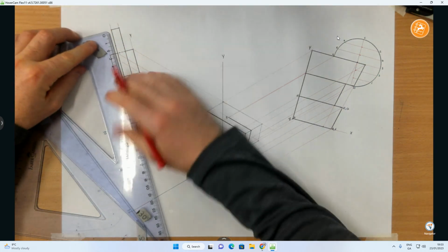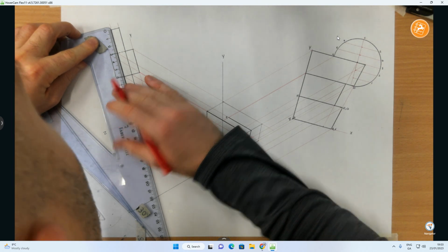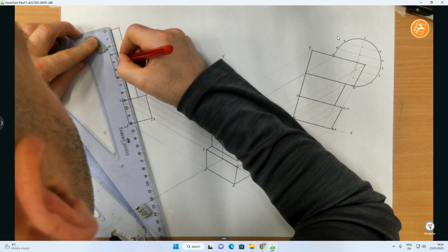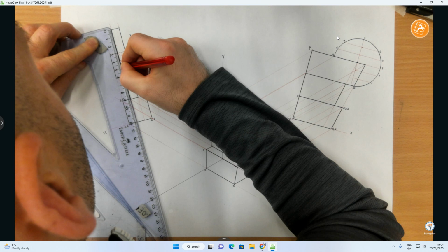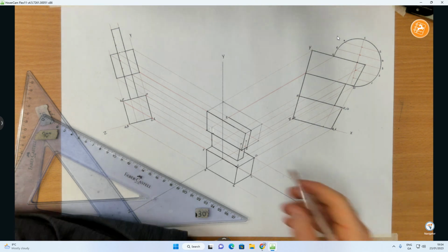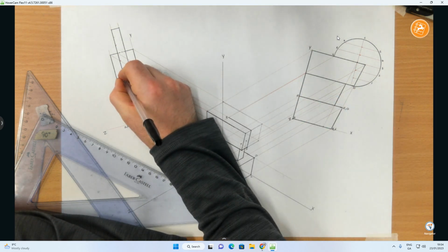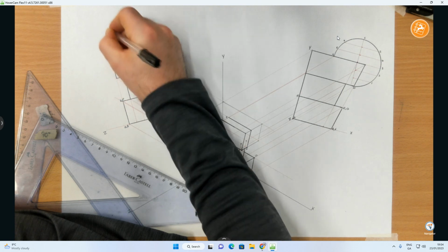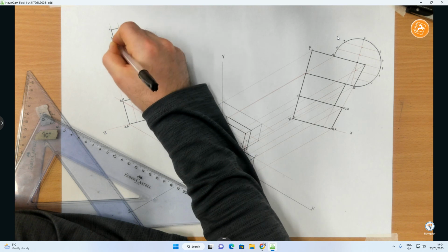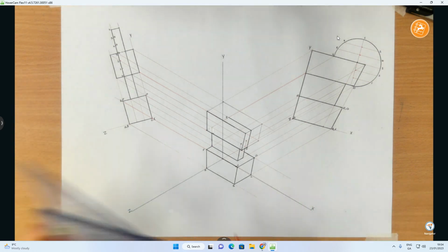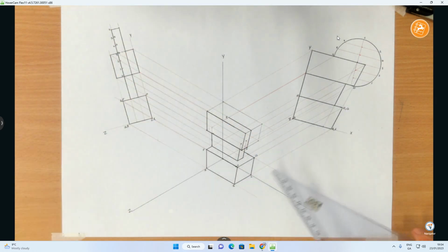So remember, it's this face that we're seeing first. So measuring down in tens: 10, 20, 30 is done already. There's the 40, and there's the 50. Using that principle, same measurements, starting at the bottom, I've got 0, 1, 2, 3 is there, 4, 5, 6, then going at the back, 7, 8, and 9. To find all of those, I'm going to follow the same rules that we used down here, 30 degrees from both directions.